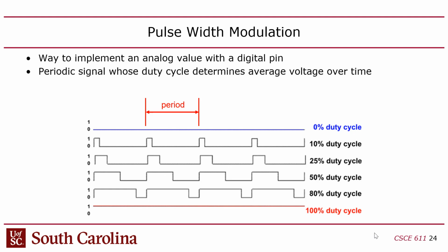Now, if you use this for audio applications, you do have to put a low-pass filter on the outside of that to eliminate artifacts from these sharp edges. But yeah, pulse width modulation is very, very common. So it's important that you understand this. Hopefully, in Lab 4, we'll use this to control a motor. That's my plan.